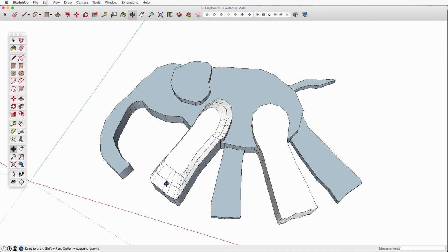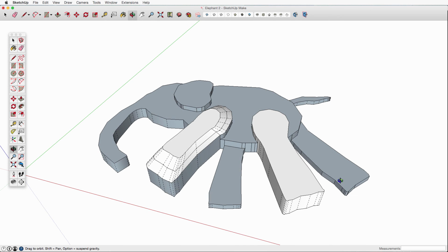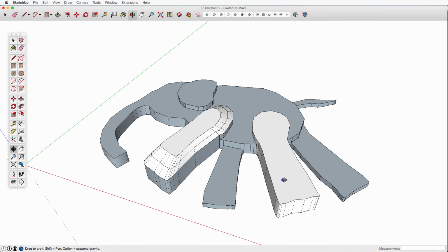And the reality is this foot would actually probably continue and be thicker at the bottom, but this will work for right now. Now to do this to the second one, we're going to hit the space bar to switch to the arrow tool and select. Press P for push-pull. Tap Option so we create that new starting face. Click. Don't drag, but we're going to hover over the line that shows the second level of the first leg. So click, and you're clicking on this leg, not over here. Press S for scale. You're going to press Option and hold it to give you that center point.